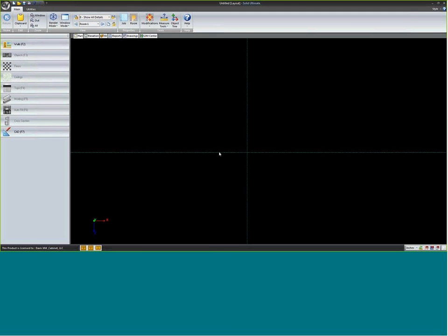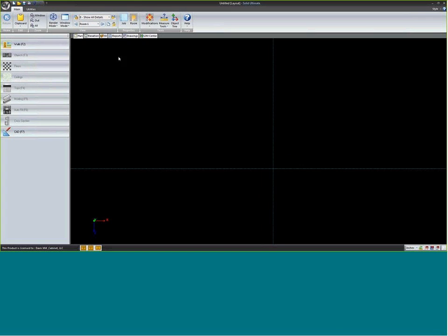Another thing I've found over time is to lay out your room in a landscape view. If you've got a widescreen monitor, particularly, you'll be able to see more of the room at once. So even if the plans from the architect show it oriented lengthwise, sometimes it's easier in Cabinet Vision to see it in landscape view. In 3D, you'll definitely see that will become important.